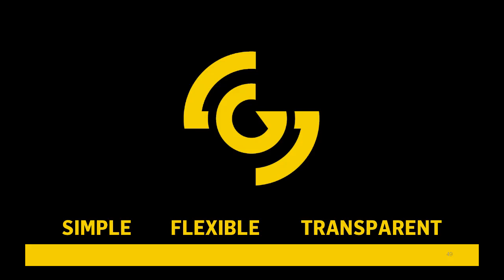All right. David Baker: we have had issues with shadows from adjacent lanes putting in false calls. All right, so that would be shadows from vehicles that we are tracking. One of the first things you need to look at in that scenario is the setup of the camera. So you want to look at the north heading, and definitely check your latitude and longitude. Basically, we use the height of the camera, the north orientation in the client, the latitude and longitude, and the time of day. Those four things are all used in calculating the position of the sun in relation to the objects that we're tracking through the intersection and the shadows that those objects will be casting.